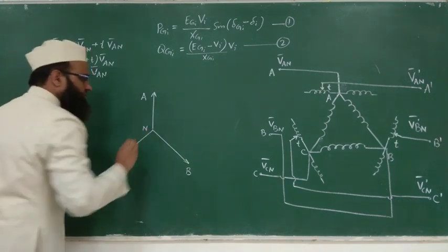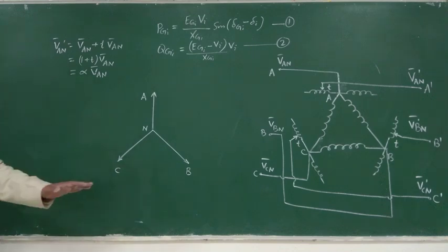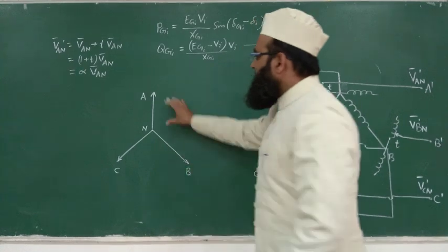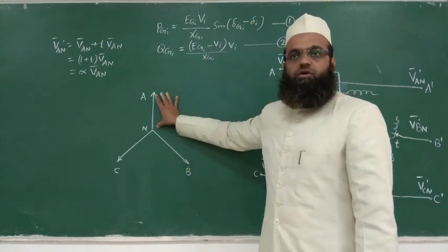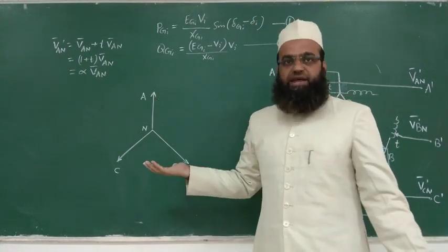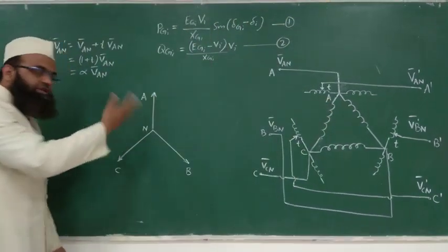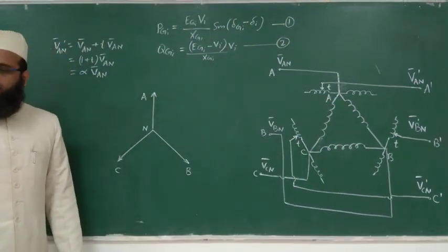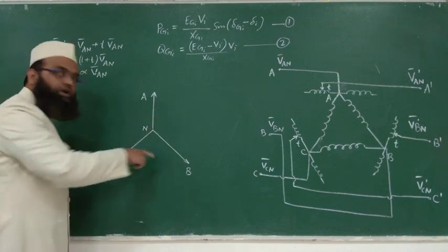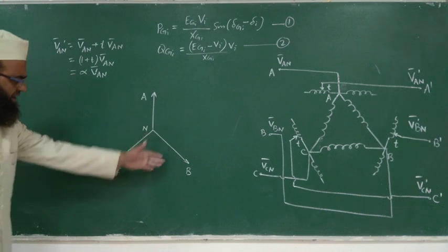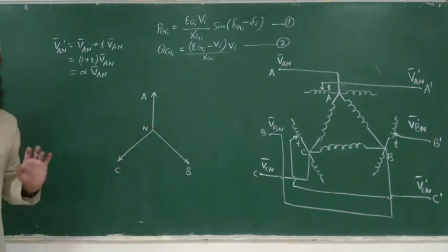Phasor diagram, you are aware of that, right? Rotating vectors. So the relative positions of this correspond to RMS values, is not it? For a three-phase balanced system, the RMS value of all three phases must be the same, and the phase difference between two consecutive phases will be 120 degrees, is not it? So let us represent it with phasors A, B, and C.